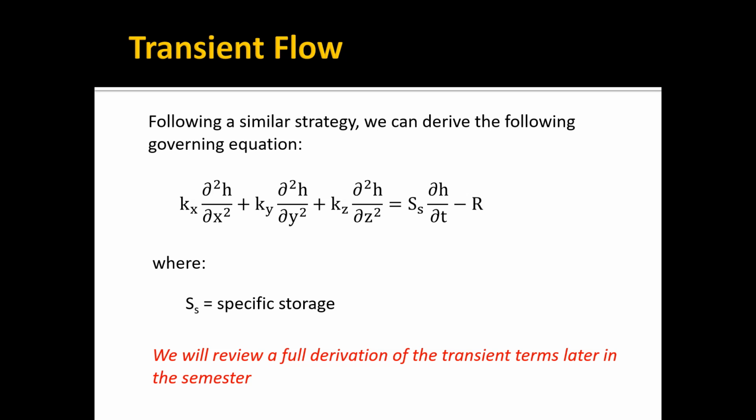So what's in front of us right here is the governing equation that's used in MODFLOW. And you'll notice that there are no off-diagonal terms. One of the assumptions in MODFLOW is that your X, Y, and Z axes are aligned with the principal axes of hydraulic conductivity. And the benefit of that is it keeps our governing equation fairly simple.